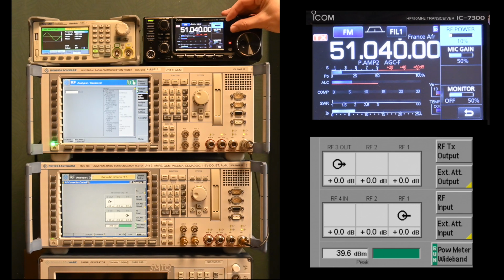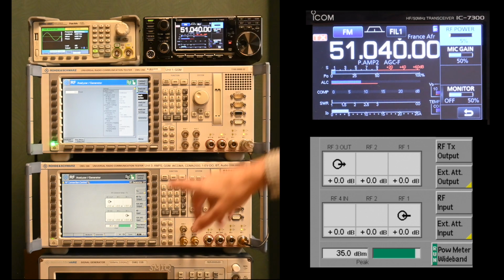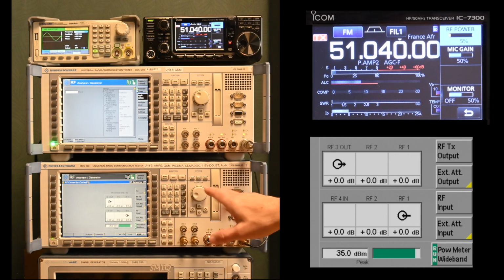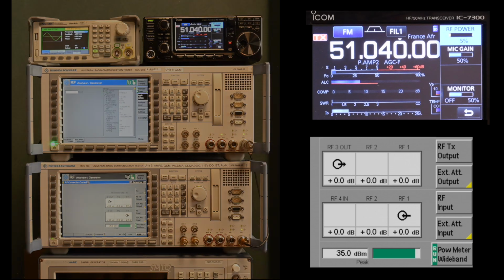Yeah, so at 39 dB I get an overload condition here, and 39 dB should be equal to approximately 9 watts already. Then it gets into overload. But this is to be expected. This is the 2 watt unit here, so we cannot expect it to deal with 50 watts like the other one. But anyway, the wideband power seems to be measuring well here on all the devices.